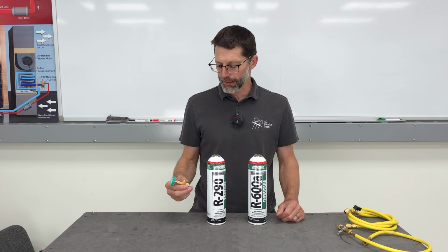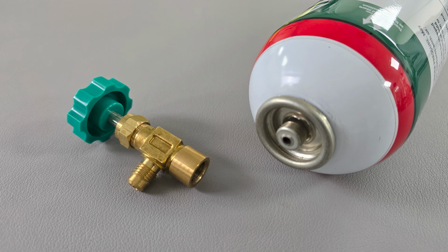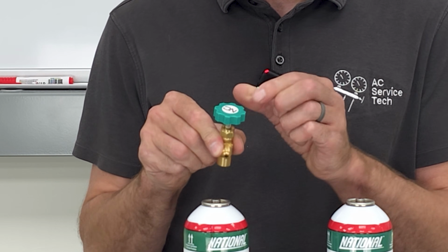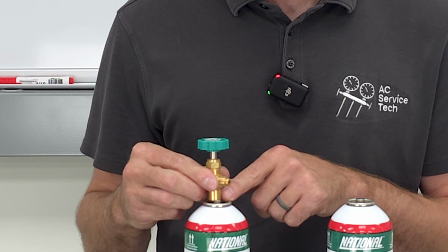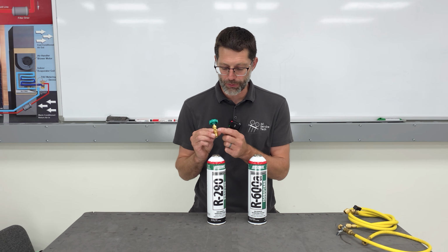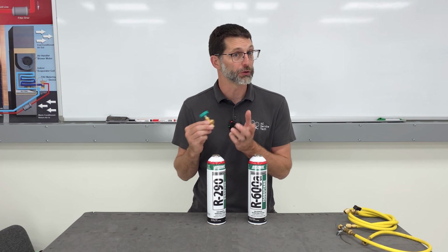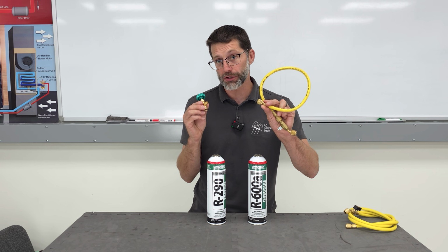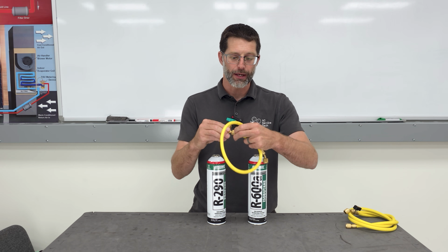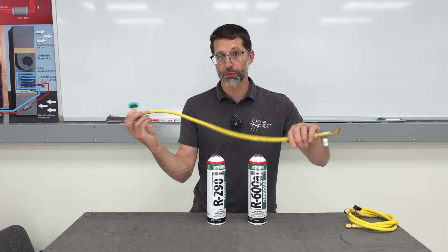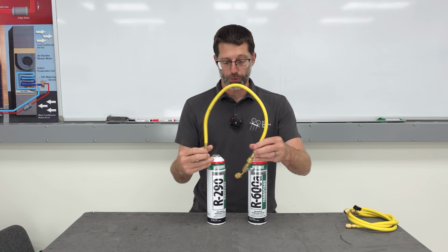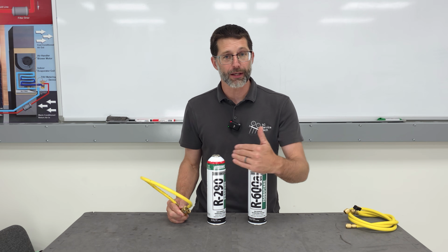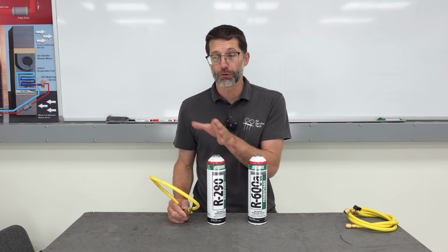And so you're going to need a valve. They don't come with a valve on the bottle. You want to make sure that this is in the open position before you screw it on. Now, the other thing is you want to make sure whether you have a valve core in the port here or you don't. This one does not. What I like to do is have the hose attached before I even screw it in. And you're also going to notice that we're using a very short hose here. It's only a 2-foot hose because we don't want to lose a bunch of refrigerant in the hose when we're, say, breaking the vacuum with refrigerant from the bottle into, say, a refrigerator.